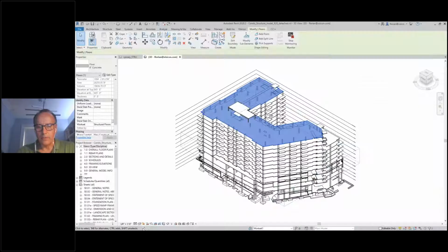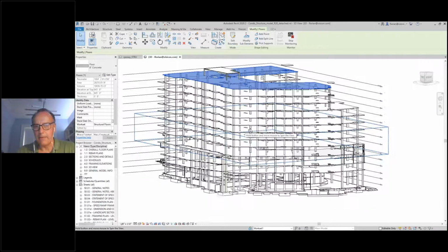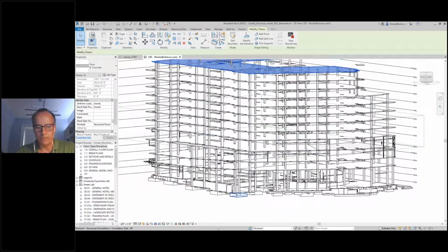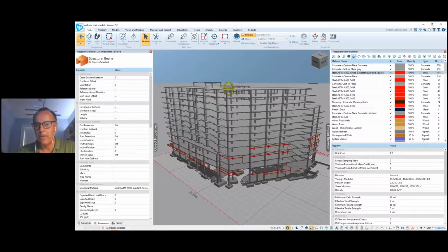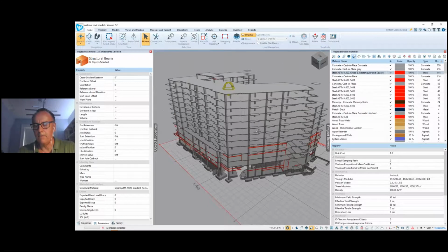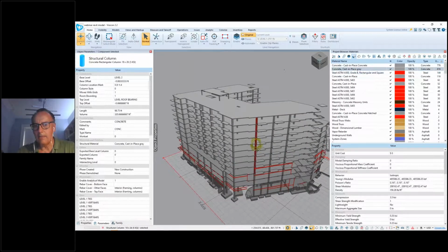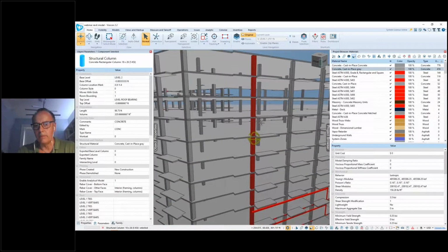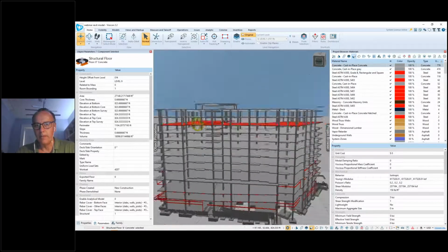Unlike Revit, right? So here, if I wanted to cut a section or navigate, yes, I can navigate a little bit like this, but it's still not that simple and straightforward to do. So what we're going to do is just spend 2-3 minutes going over the basic navigation capabilities of Visicon. So you can see this orbital. The default is wherever you click and depress your left mouse button, that becomes your center of rotation. So you see it's that simple to be able to rotate it.